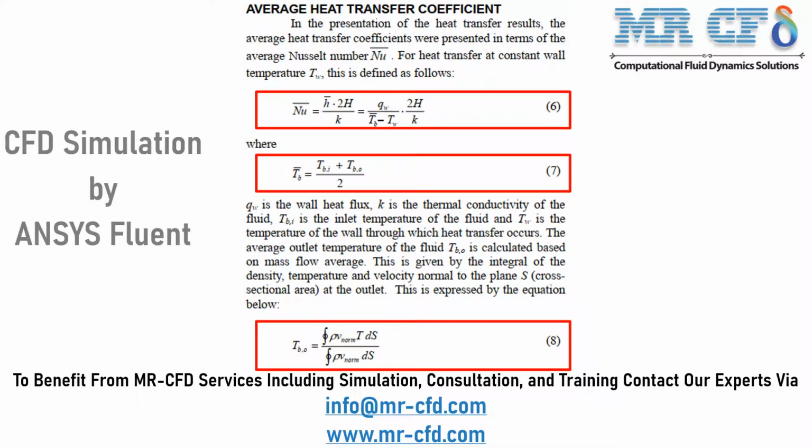In this slide we have extracted a part of the paper's text in which you can see different equations. Equation 6 shows the formula to calculate the Nusselt number. Now in this equation you can see that the Nusselt number requires an average temperature, and that average temperature is defined to be the average temperature of the outlet and inlet boundary.